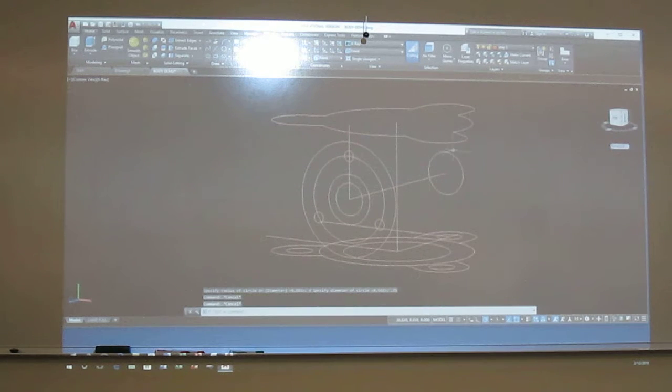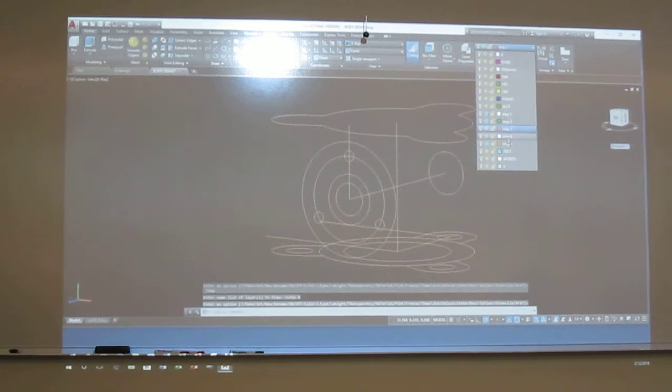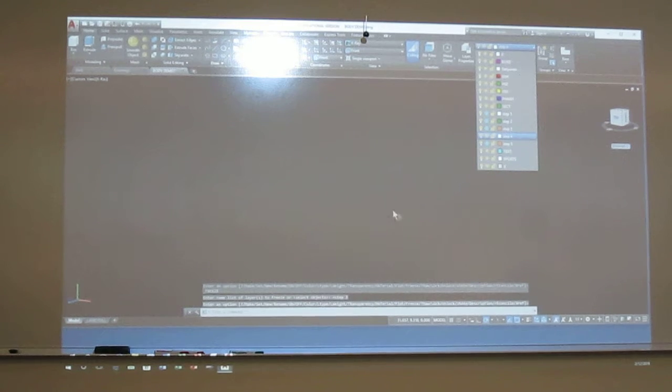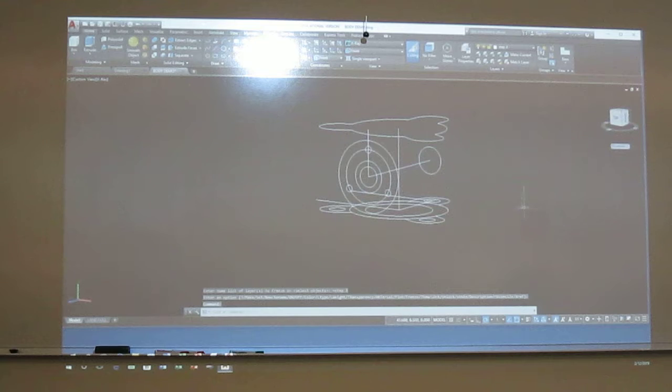Now, I wanted to kind of leave this step alone, although I am now ready to complete this and go to my Boolean operators. So I'm going to use extrude, revolve, sweep, loft, one of those, or all of them, and then Boolean operator. I've set that up in step 4 so I can walk through the process of it. So it's the same as step 3 here, it's just been copied over. So I'm just going to zip over to step 4 so that this is retained. And it's right here, and I'll show you how I'm going to do it.